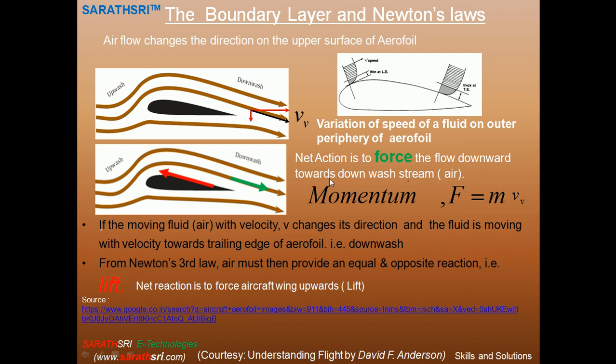So with these two main reasons, one is Bernoulli's law and the other one is this momentum principle, Newton's third law, the lift is happening in the aircraft. So there are many theories responsible for this lift. However, this is our understanding: the curved surface, the Coanda effect, the surface boundary layer. There are many things that are also responsible for this.